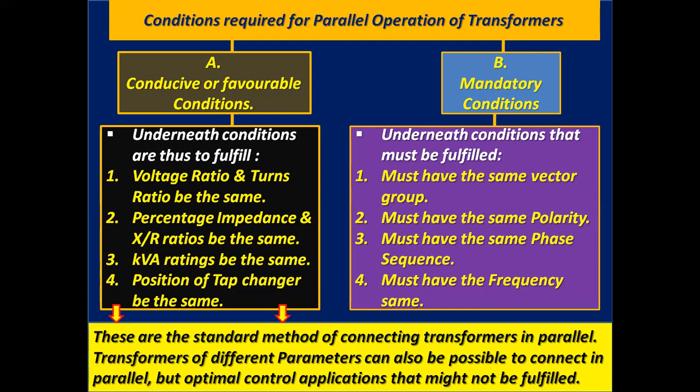And B is the mandatory conditions. 1, must have the same vector group. 2, must have the same polarity. 3, must have the same phase sequence. 4, must have the same frequency.